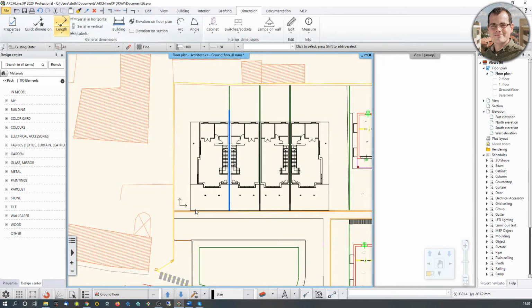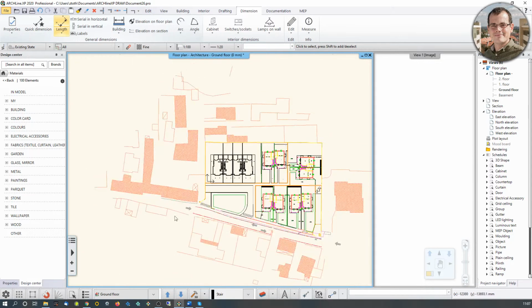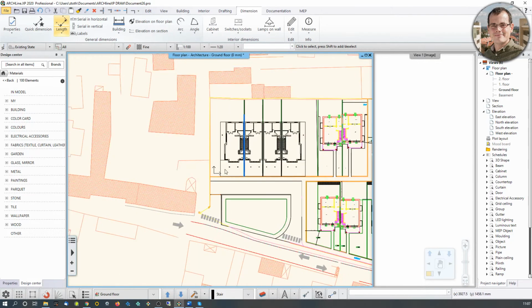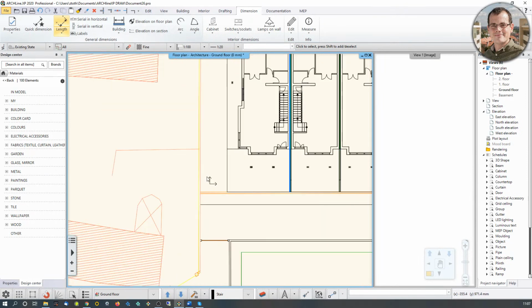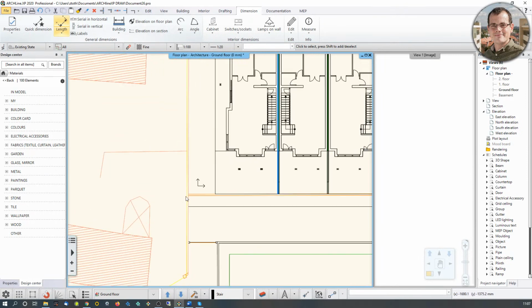Now, let's return to this project origin topic for a second, because this is a major issue if you're working on large DXF DWG drawings. If you are working on a drawing where the origin is very far away, let's say a couple of 100 kilometers away from where you need it, then you might have calculation issues. And let's see, how do you fix that? How do you move the project origin? Let's say I want to move the origin over to the fence over here.